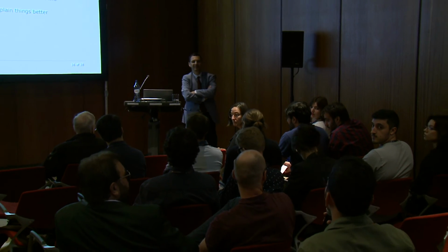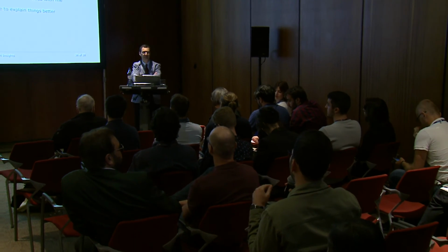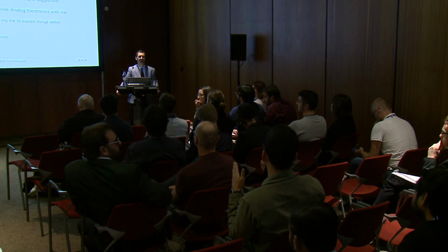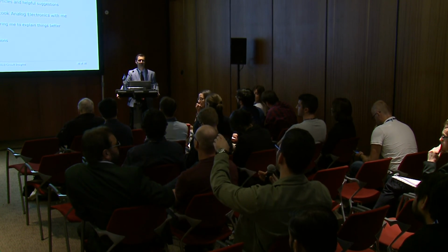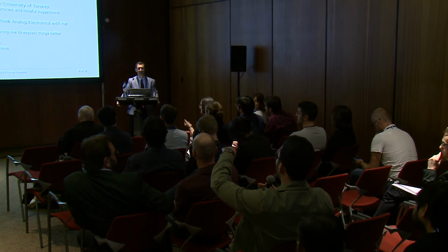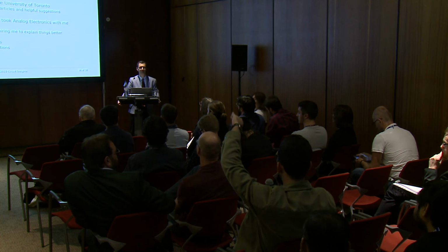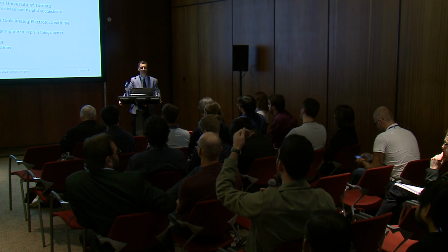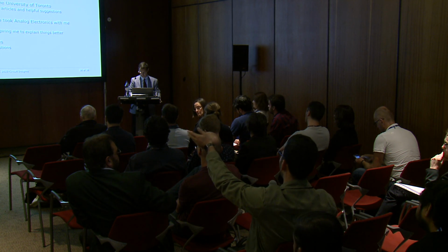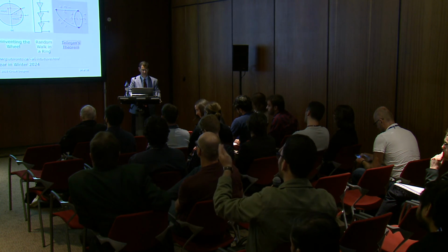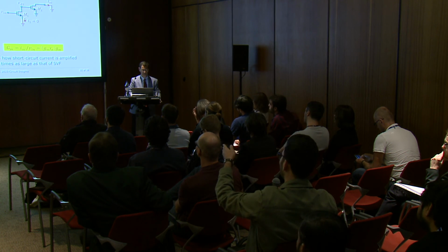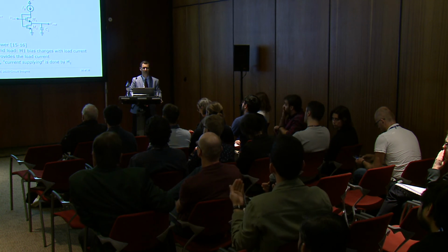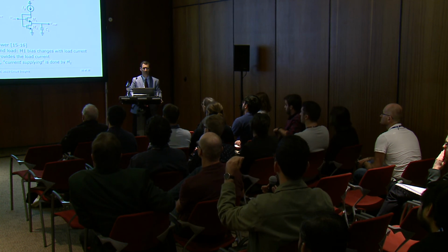Yes, my name is Erwin. I have a question regarding the limit, where you put the limit for your intuition. For example, for the voltage follower, you didn't consider the effect of the current source on top, and we assume that M1 doesn't have any current, and we know that that node will affect many parameters, including the gain and then the stability of the system. So normally, how do you define the limit for making it simple?